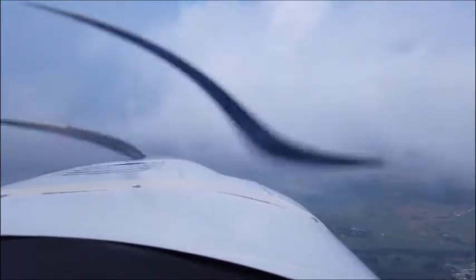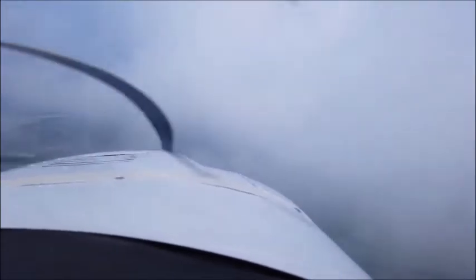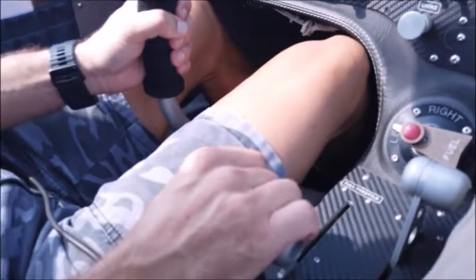So here we're going to be doing a flight through a cloud, just to demonstrate how important it is to use instrumentation. And as you can see, as we're going through this cloud, you're starting to see less visibility, you can't see the horizon, and you need to rely on your instruments to know what orientation you are in terms of the pitch of the aircraft, the roll of the aircraft, and the yaw of the aircraft. And if you don't have this, it could cause major issues.